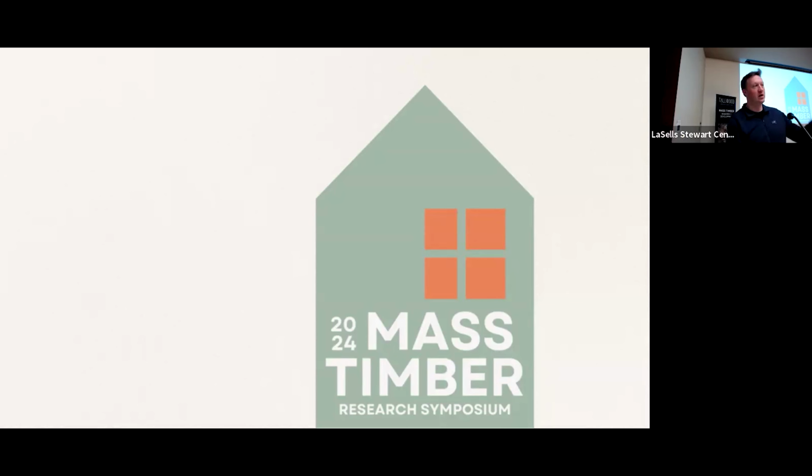So imagine the end of the robot has something that can tell it in which direction the force is when it pushes. And then there is a feedback loop that we can adjust the movement. So rather than normal path planning with a robot, where it's offline planning and you say go to this coordinate or this plane system, here the robot is actually asking back to the server every, I don't know, 10, 12 milliseconds where it should go next. And then in the background, there is a calculation saying, okay, if there is this much force, then go here, if not. So you're calculating the path more live. That's the simple way to explain it.